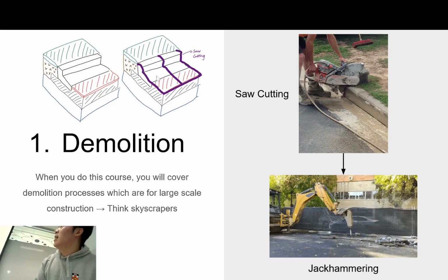Yeah. So you're cutting along the concrete here to make small sections. So these are relief cuts, right? And then also, you need to cut along the road surface as well. So the reason that we cut along the road surface in this case is we want to make sure that the curb and the concrete looks super, super nice, right? And you can't edge the concrete, you can't make it look super nice if there's a road in the way, right?